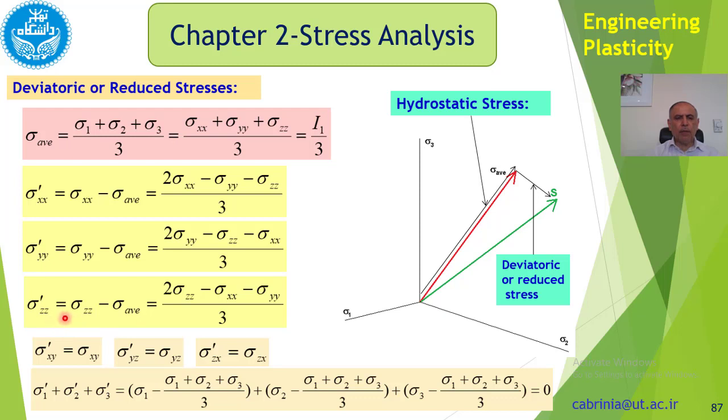So we don't have any hydrostatic pressure which could be reduced from them, because they are themselves shear stresses, not normal stresses, so that we could subtract the hydrostatic stress. Okay, because this hydrostatic stress, as shown here, is in terms of the normal components or the principal components, no shear stresses. So that's what we have here.